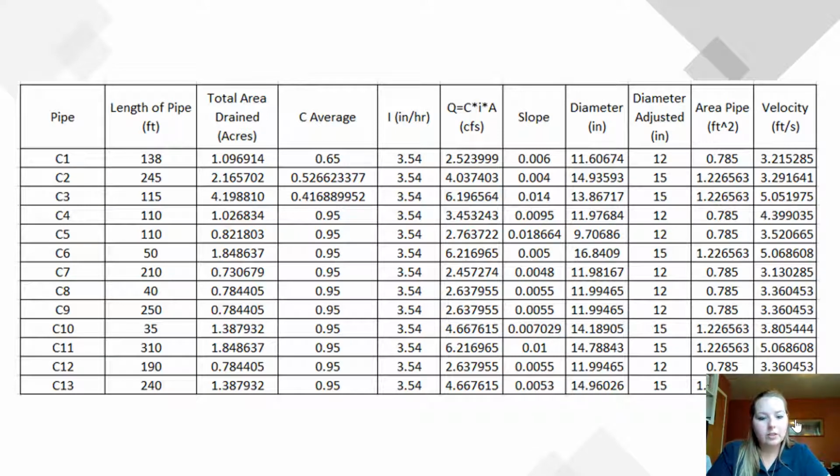At first, the road was divided into various subcatchments, assuming the crown was in the middle of the road. However, the velocity in the pipes collecting runoff from these subcatchments was under 3 feet per second. The slope could not be realistically adjusted to fix that issue. Therefore, the subcatchment areas on the roadway needed to be increased.